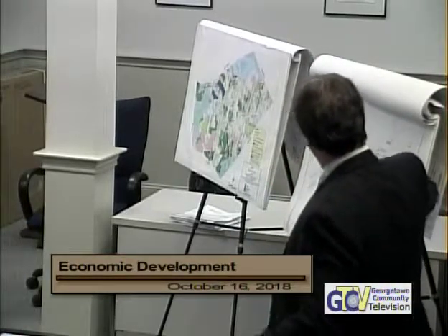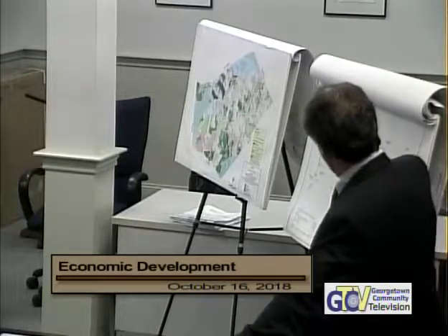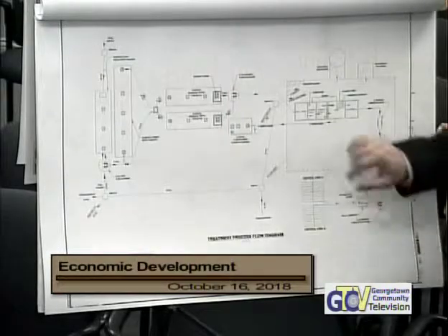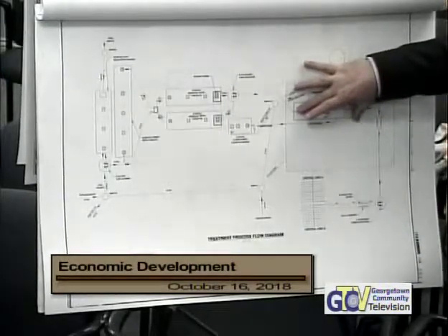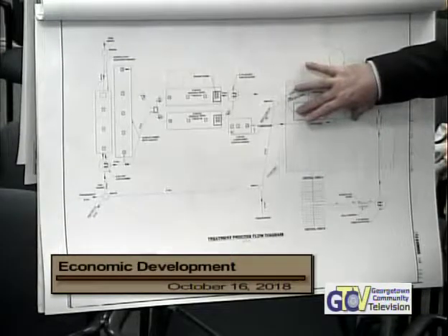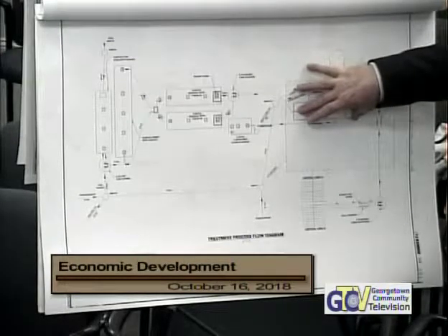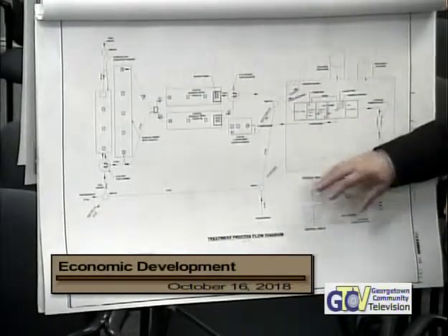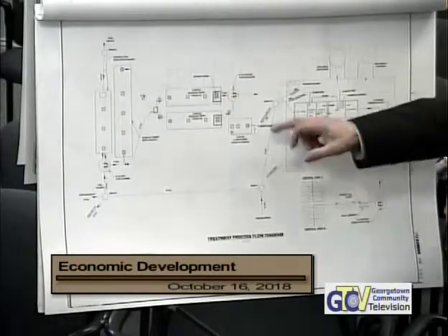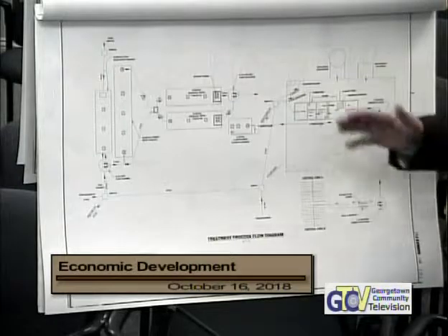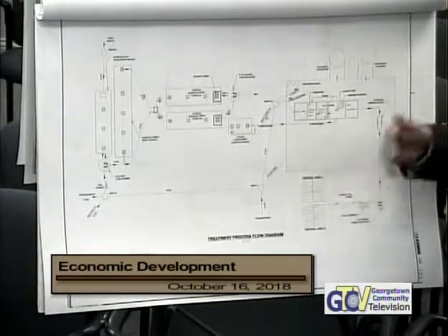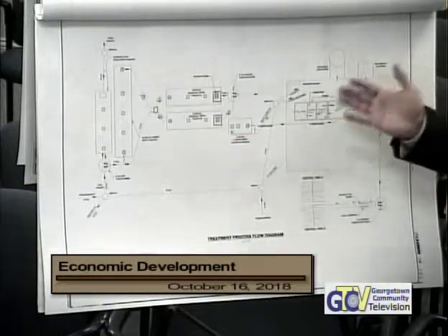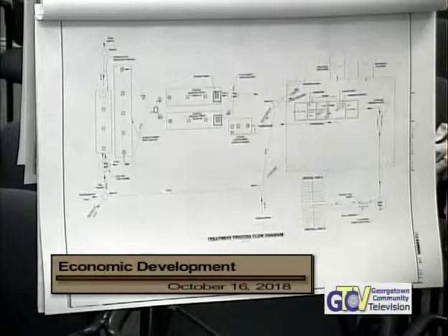In this case here, after the membrane system in treatment, and this was a package unit, I think for this 60,000 gallon per day plant, the treatment process itself here was about roughly $450,000 from the vendor. Installed had another 100,000, so about 550 for the process. But you also have a treatment building, peripheral equipment, chemical feed, all the tanks. By the time you get done, 60,000 gallons per day was the equivalent of about 1.2 million. Okay? Not counting the collection system. Just the treatment process.